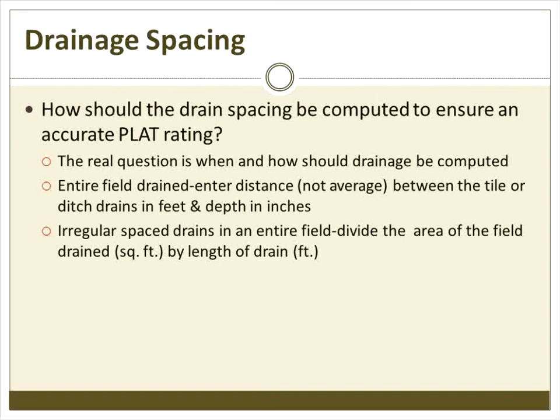And if that field has the potential to be drained, you will be asked automatically in the program to enter the distance between drains, either drainage tiles or drainage ditches, in feet, and you will be asked the depth of those drainage ditches or tile in inches.